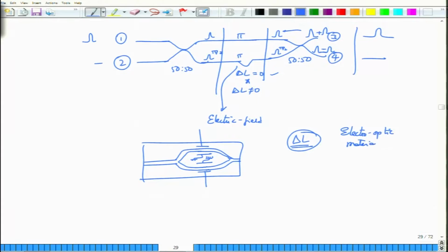And with electro-optic materials, the idea here is that when you apply a certain voltage V, then that will change the refractive index by a factor of delta n, and you can actually obtain the desired phase shift between the two arms, and then formulate a Mach-Zehnder interferometer here. Of course, in this Mach-Zehnder interferometer there is only one input port and one output port. So when this device is made in this way, and you launch light and keep the phase shift between the two arms the same, then these two paths will propagate, meet and be reinforced with each other.